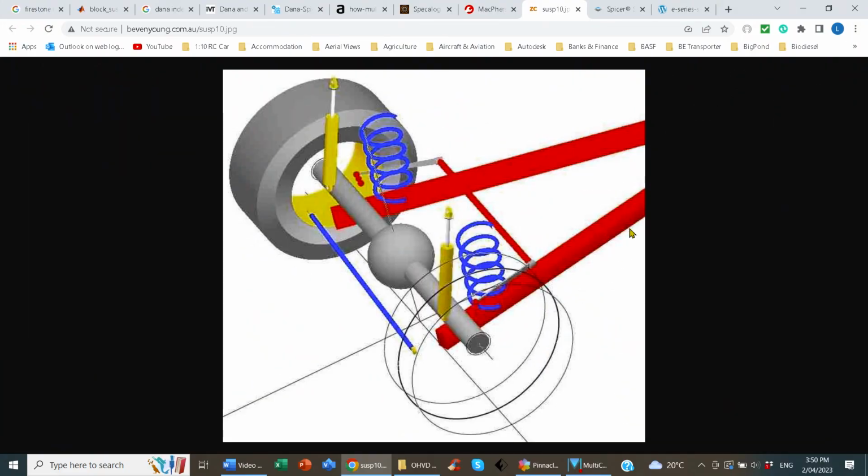Now, neither of these types I've just talked about, equalizing beams and walking beams, have springs. So they don't actually absorb energy from the road. Moving on to things that were originally done for on-highway, we'll talk about leading and trailing arms. Variety of ways it can be done, A-frames and independent arms and all sorts of things.